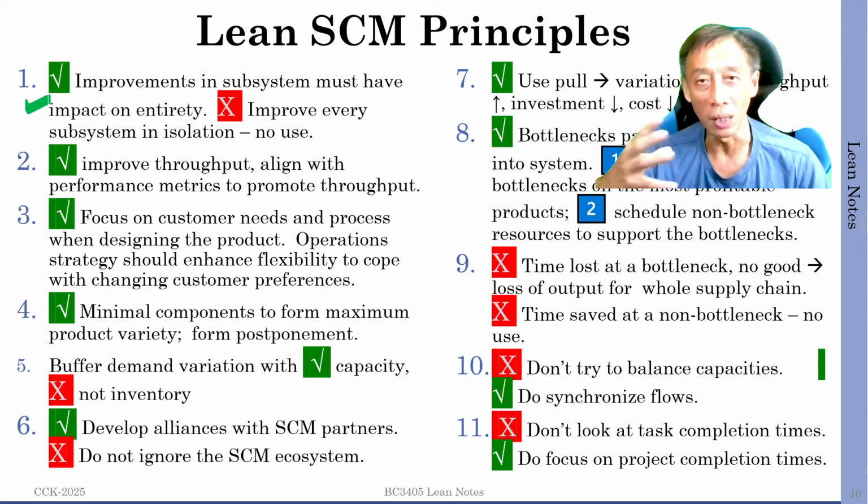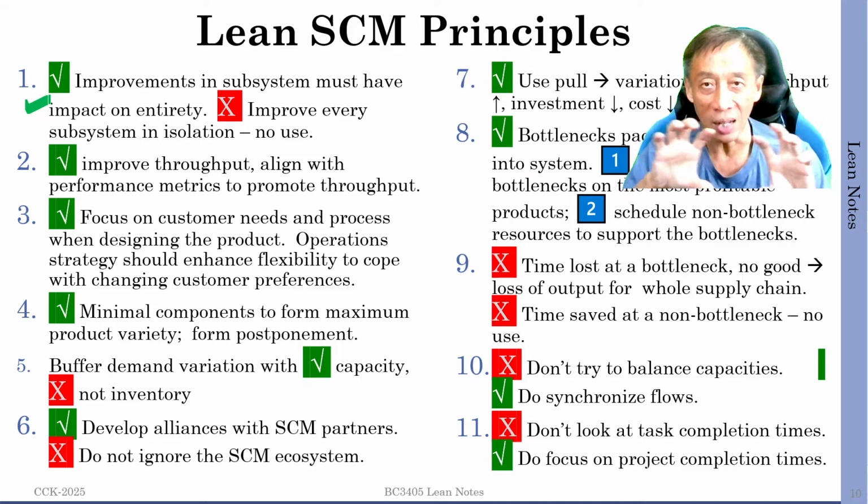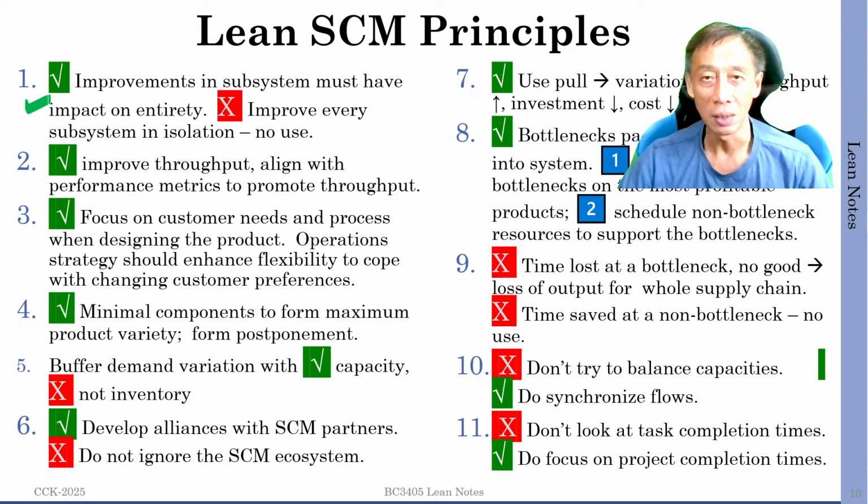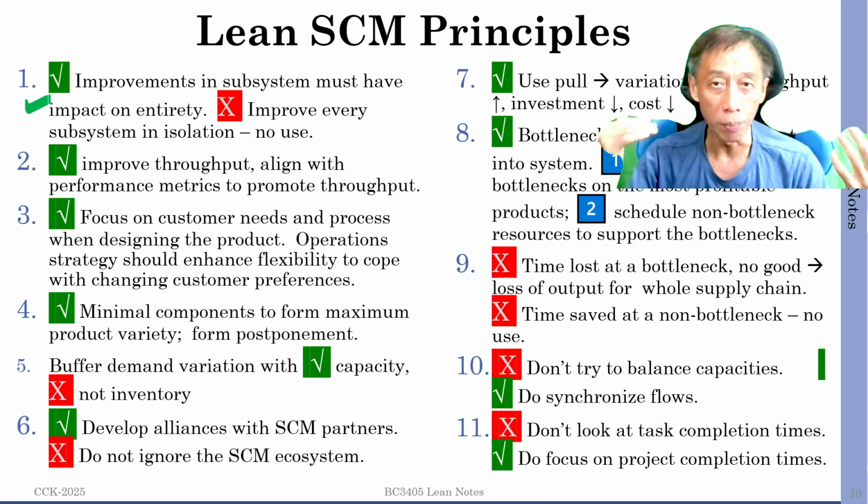Maybe you think that the effective capacity has increased, but then you are improving a non-bottleneck. So after spending all the upgrading and improvement work, the entire process capacity hasn't improved because the bottleneck capacity stays the same. So there's no point trying to keep improving non-bottleneck resources.